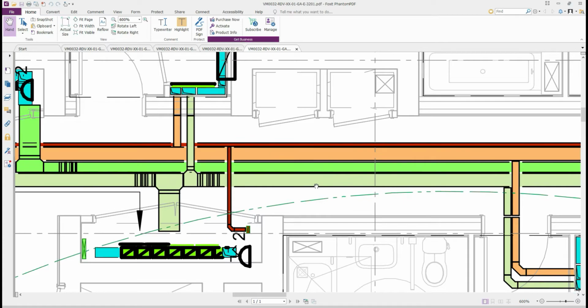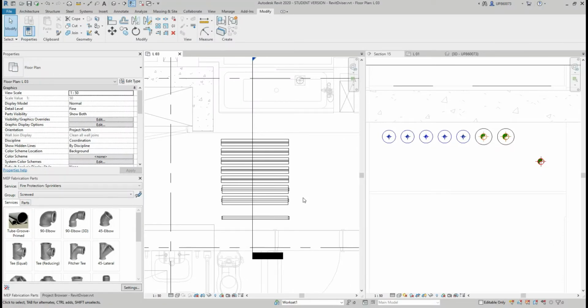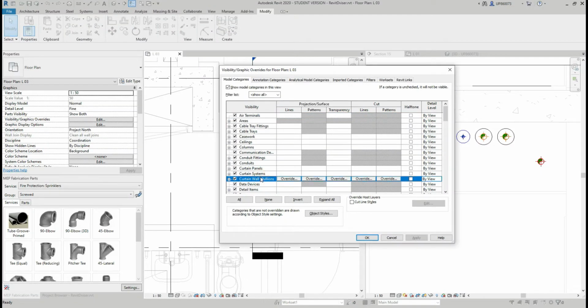fire alarm tray. I'm gonna position them at the height so there is 100 mil distance between the underside of the ceiling and the underside of the containment to allow some room for light. Let's model it, and the first thing I'm gonna do is hide the pipes.